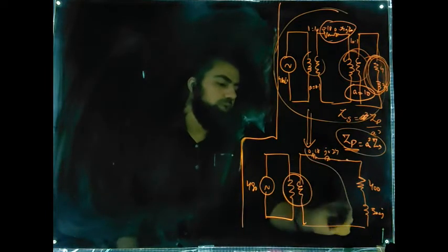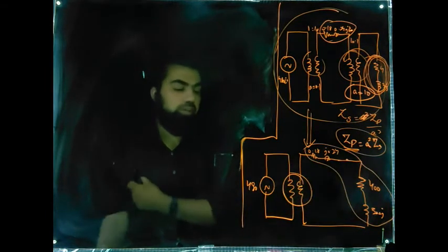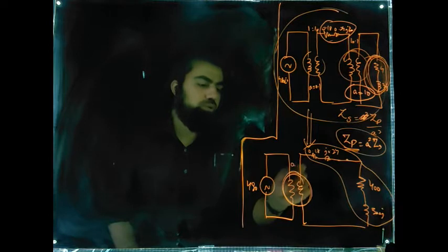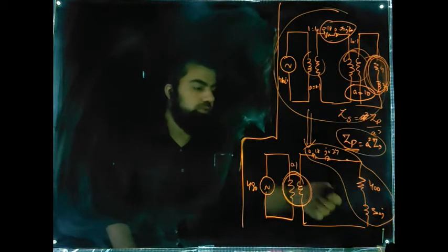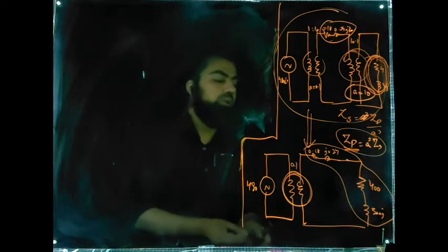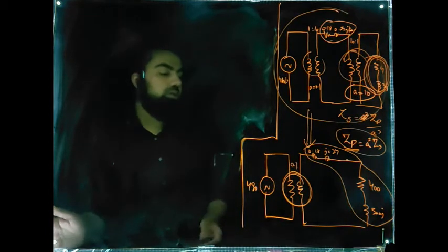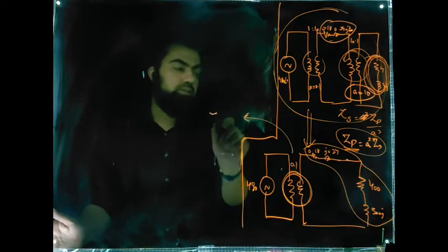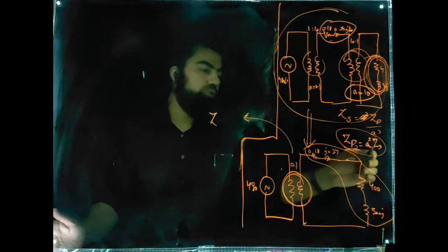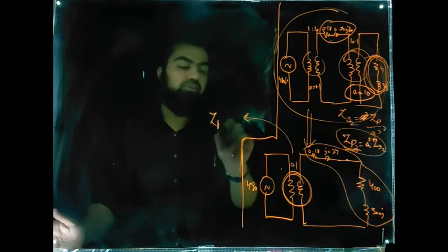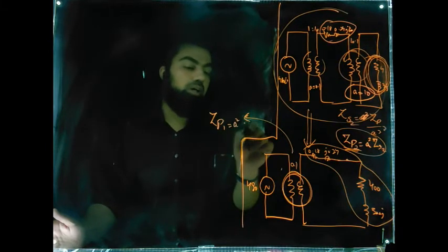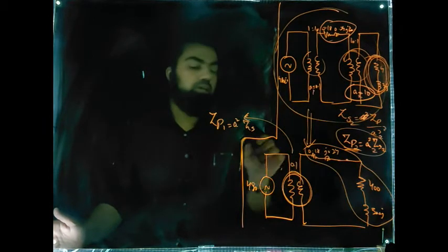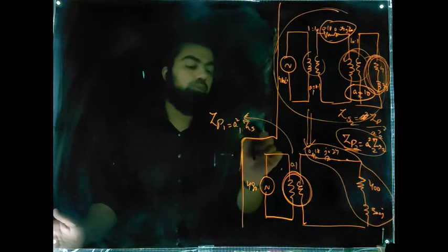Now this is your total impedance. Again, this is your impedance on the secondary side of this transformer. So what we can say is, if the transformation ratio is now 0.1, this impedance when referred to the primary will become equal to 0.1 square times Zs. So for this transformer, if this is Zp2, Zs2, this will be Zp1 equal to a square Zs, and I will also write A2, this is A2, this is A1. So this is A1 square times Zs1.